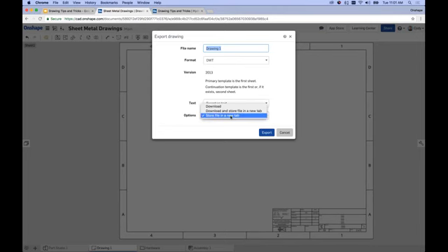Essentially, this is going to take whatever drawing you're looking at. It's going to save it as a DWT file in this document, if you choose Store File in a new tab. Now, every time that you go to create a new drawing, you're going to get this template as an option, right? So important thing to stress, if it were me, I would go into a new document, create some blank drawings, set all these things up, and then export and save as DWT.